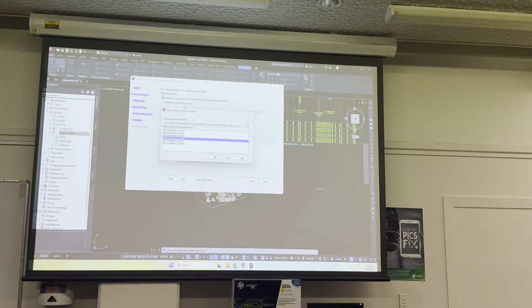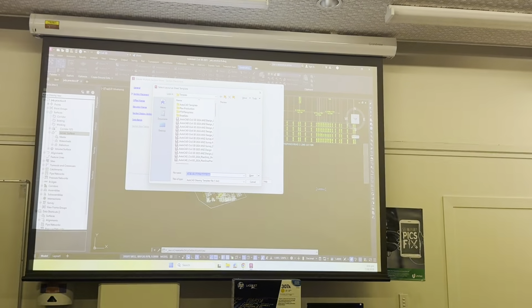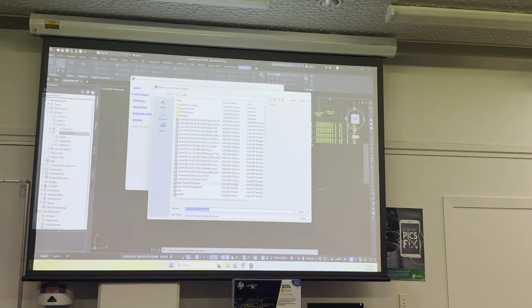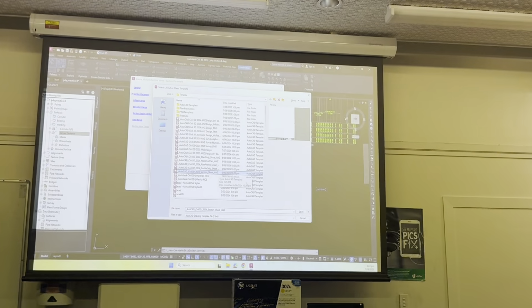Sorry, we click this button again. We click this, three dots, and click these three buttons. Sorry, these three dots. Click it again. You can choose the AutoCAD Civil 3D section sheet ANZ. So if you expand this, you will see the AutoCAD Civil 3D 2024 section sheet ANZ. Should be over here, just above the Autodesk Civil 3D Imperial. Just click on that and click open.